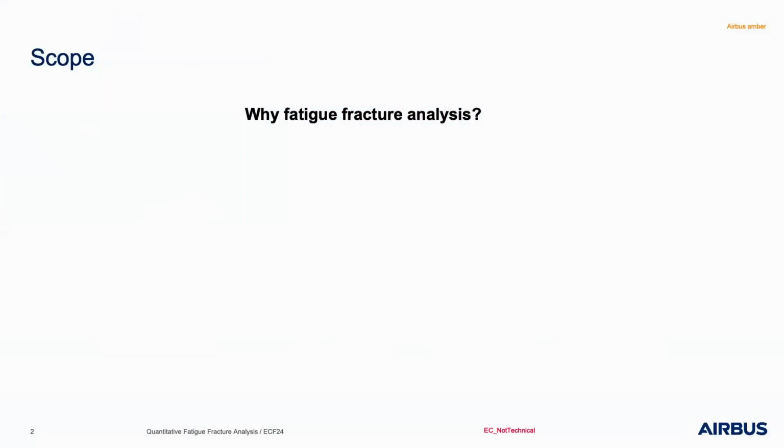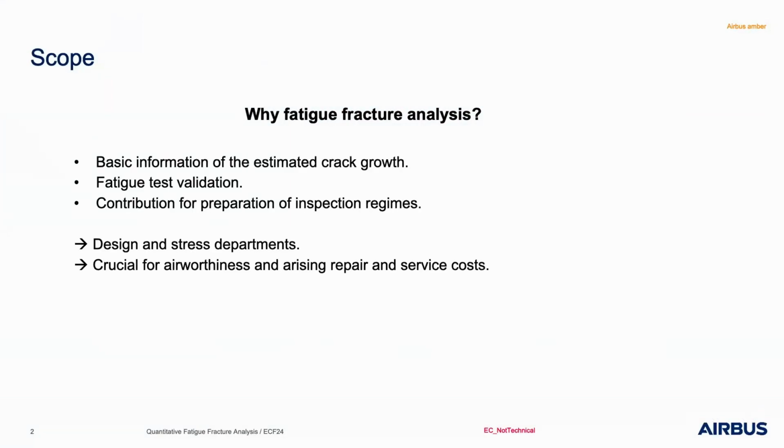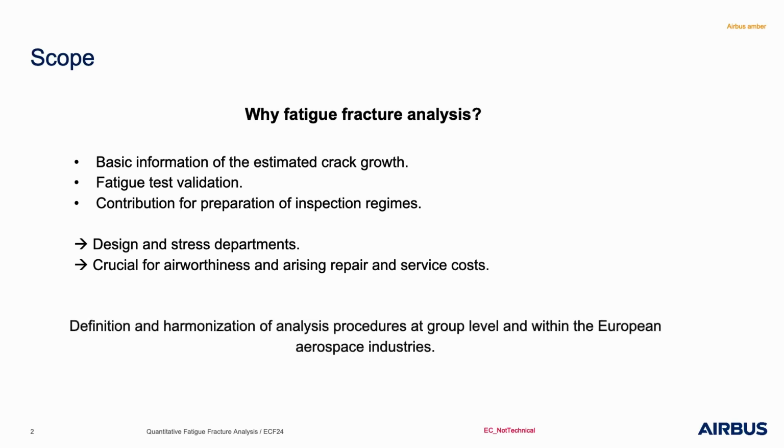At first, why fatigue fracture analysis in general? For us, it's the basic information of the estimated crack growth. It's the fatigue test validation and also a contribution for the preparation of inspection regimes. This means the inspection during in-service as well as the first part inspection. It's required and useful for our stress and design departments and really crucial for airworthiness and, at last, the arising repair and service costs.